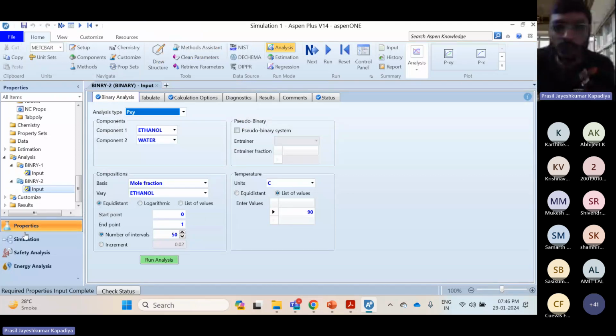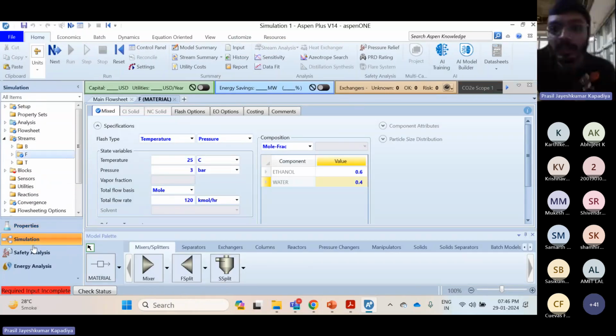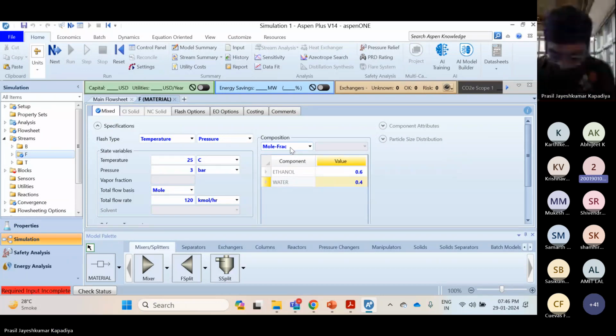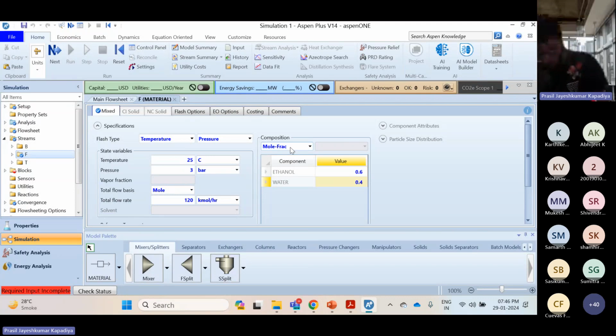Now, one more thing I want to show, but I am not sure if it will work or not because I have not tried. But let's try here only. We know that ethanol water forms an azeotrope, right? Does anyone know the azeotropic conditions? What is the condition? 97% ethanol, I thought so. 97 what percent? Weight percent? It is 96 weight fraction ethanol and 4 weight fraction water. If we convert it into mole fraction, it is around 87 and 13, I'm not sure of the exact value.